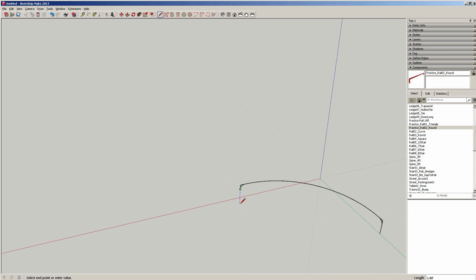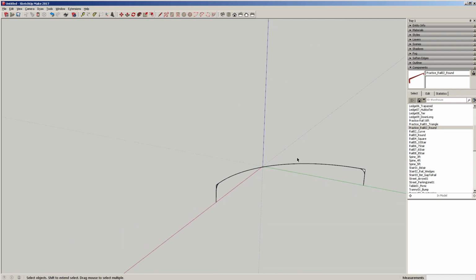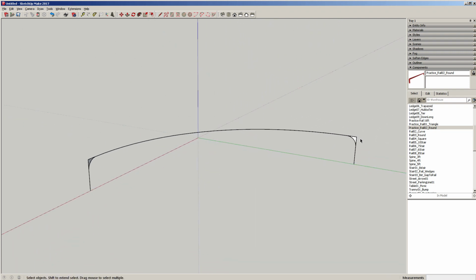So how would we snap to the same line here, vertically here? Ooh, do you see that? From point. Nice feature. Otherwise, you would hold Shift and just put your mouse on this edge. You're not making a line to this edge, you're just using it as a snap reference. Now you can simply draw a little rectangle, delete the rest of our face here.